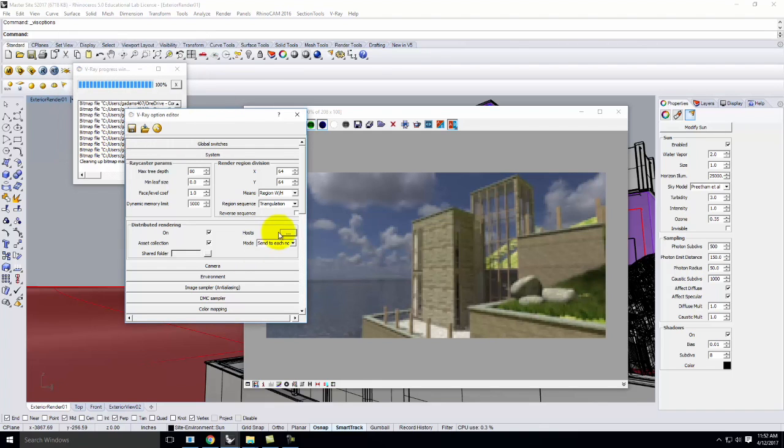I do these in groups of 5 to try to make V-Ray not crash. If you do all 24 at once, it's about a 50-50 shot whether V-Ray crashes or not. So if you do them in groups of 5, generally you're OK, and you can come back. Notice that I save my VisOp just in case beforehand, and we can save Rhino and then bring it back.